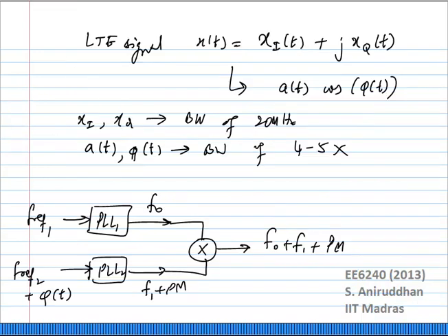The problem with this is that as you keep going to wider and wider bandwidth signals, and with larger and larger peak to average ratio, which is a definition, an indication of how dense the signal is, if you try to pack in more and more modulation, then even though the signal itself in the Cartesian domain may be limited to a certain bandwidth, you will find that if you try to split the signal from its I and Q components into its amplitude and phase components, the bandwidth of these two is actually much wider than the original signal itself.